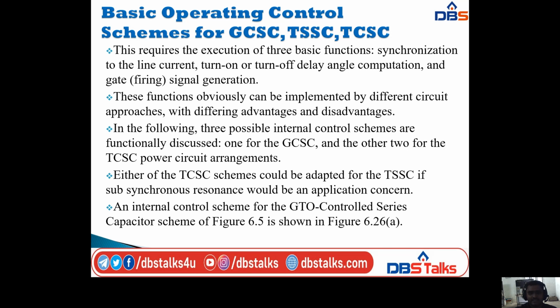This requires the execution of three basic functions: synchronization to the line current, turn on and turn off delay angle computation, and gate signal generation or gate firing signal generation. These functions obviously can be implemented by different circuit approaches with different advantages and disadvantages.